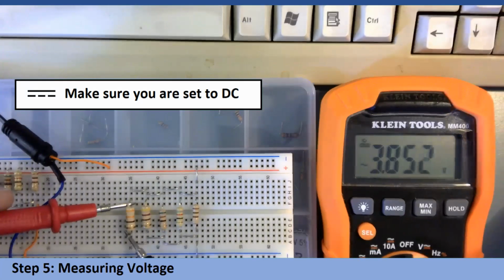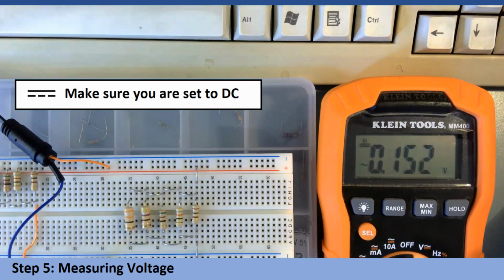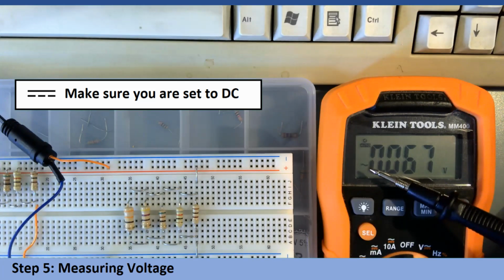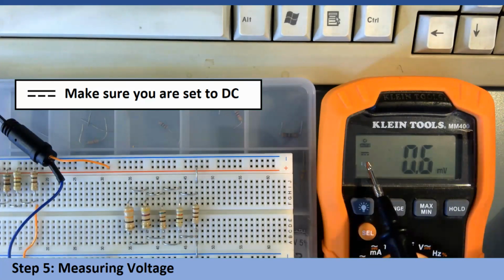And I'm getting it jumping and numbers that don't make sense. That's because I have forgotten that right now it is on alternating current. So I'm going to press my select. I see I have my flat line.